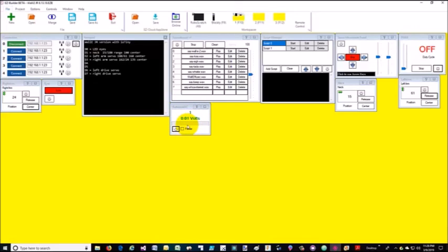And really what you're replicating, if you think about it, is a potentiometer in a way. That's the way I think about it. If you understand what a potentiometer is, it's a variable resistor, right? You could hook that up to the ADC line, and if you manually turned the variable resistor up and down, you'd be able to see the readings here go up and down as you turned the control.